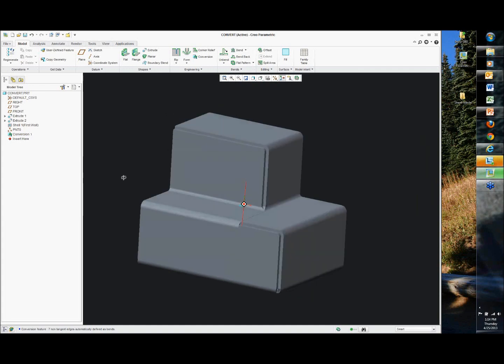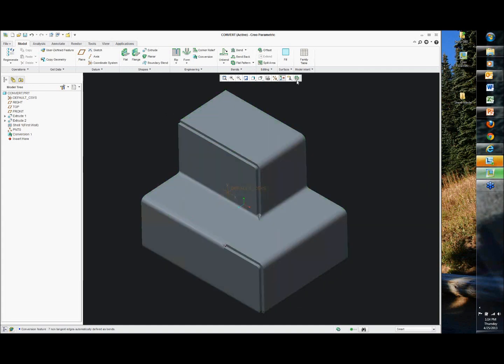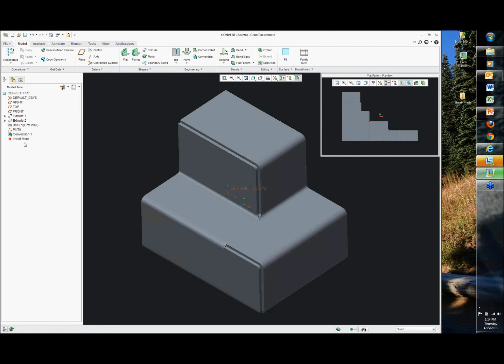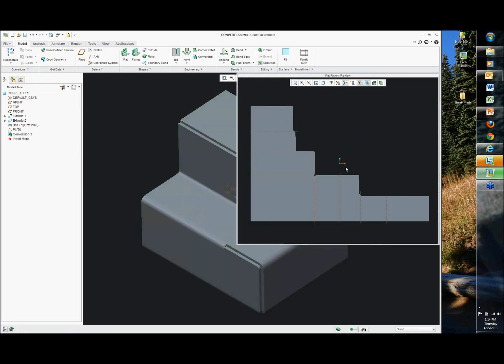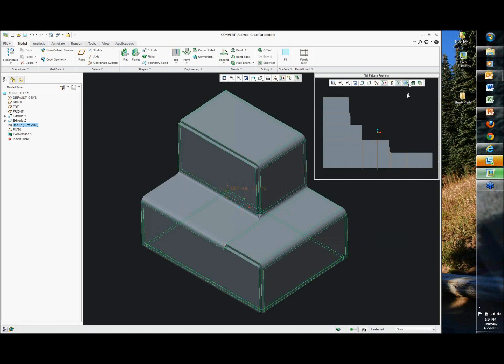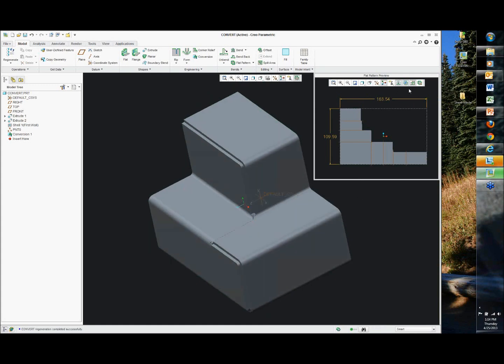Now, at least I've got it so that it will make a flat pattern, and we can use that preview tool we talked about a little bit. So there's the flat pattern preview button, and it's just a simple button. It didn't make a feature. It didn't add anything to your model tree. It's just simply a button to look at the way this is. And I can make it bigger or smaller, right, just by dragging the corner here. I can add the bounding box information, right? So again, these are just preview type buttons that I can add and just pick. If I want to make a flat state of it now, I can use the flat state. We'll do that a little bit later.